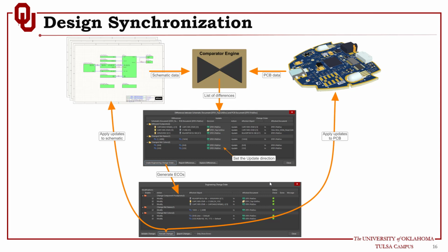As we saw a little bit when we changed the color, we were able to commit the changes from the schematic to the layout, and then we did some changes on the layout, and also we were able to commit these changes the other way around, backward. Now, whenever you try to commit changes, an engineering change order, or ECO, will be created. These are then applied, bringing the two sides of the design back in sync between the schematic and the layout.